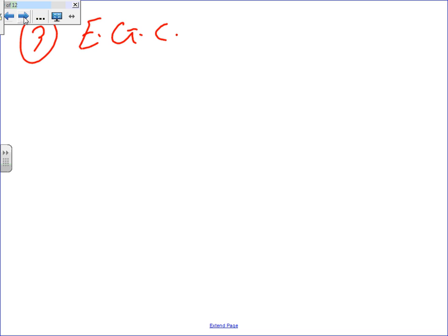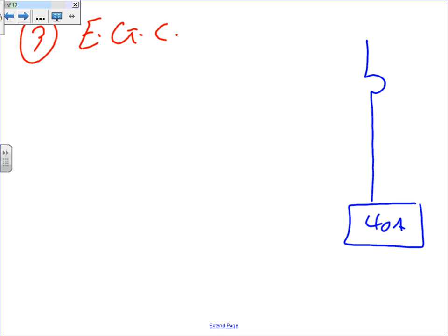Here's the situation that I have. I have an overcurrent protection device tied to an equipment, 40 amps. This is 80 amps. Did we say 80 amps? This conductor is a number 8 conductor. This is a welder.